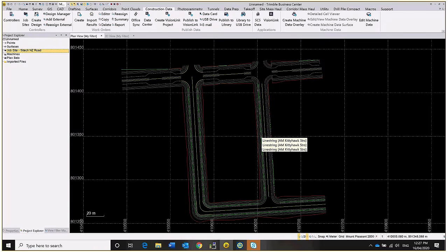Sweet, so that's done. So now you could take out your USB stick, go up to a GCS 900 machine, or a CB460, 450, 430, and just plug it in and upload the design, and it should just work. If you have any issues, just feel free to contact support. Or try the 12.4. Definitely try the 12.4 if it doesn't work.